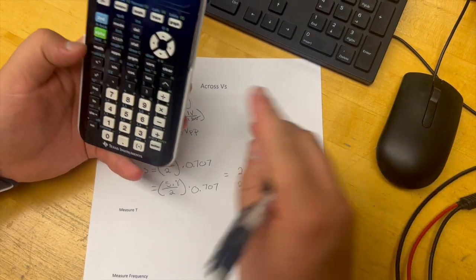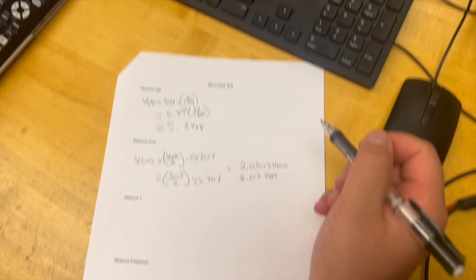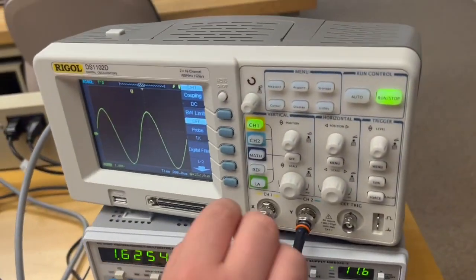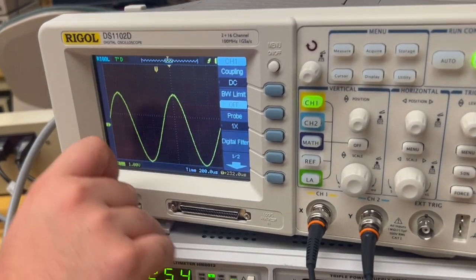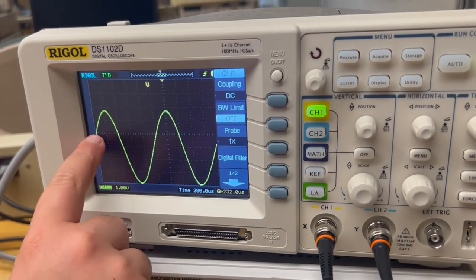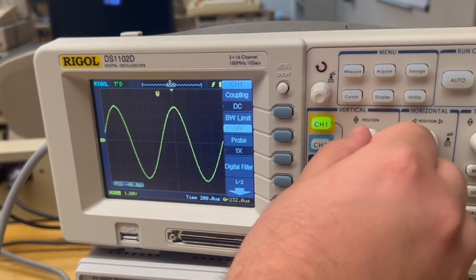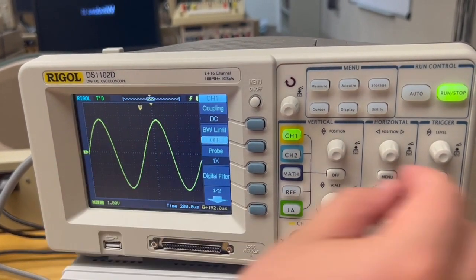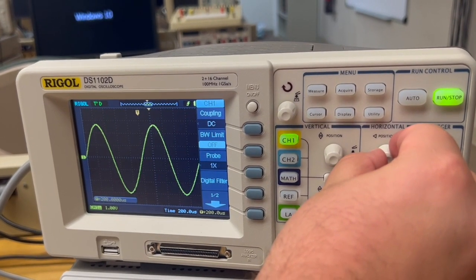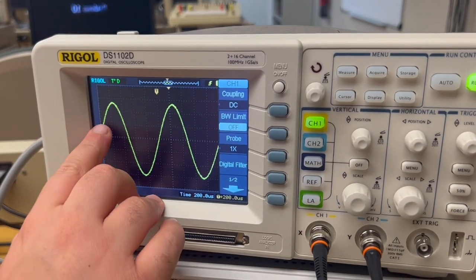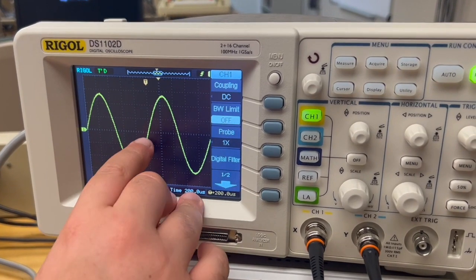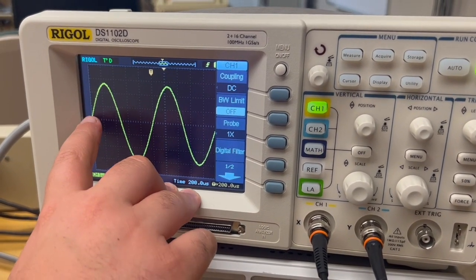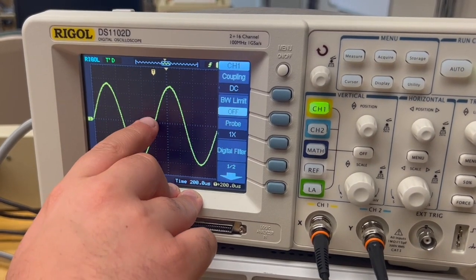Okay, now we're going to measure our time. To measure our time, we're going to go back to our oscilloscope here. The first thing you want to do is put this right here to the center line, so we're going to position it right up here. Then we're going to position it a little bit horizontally until we see the positive touching the 0 right at the edge here. Now we're going to count straight across until we see the next positive beginning. This is going to be one full cycle for the time. So we're going to go 1, 2, 3, 4, 5.